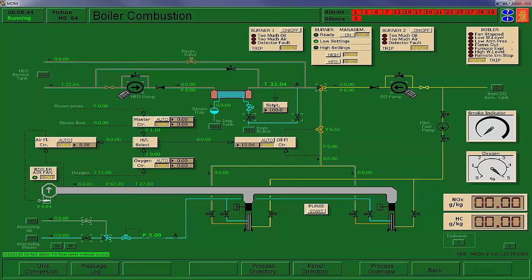Now, any boiler that you go to, you're going to have to play with the settings. But about 15% firing rate for startup is a pretty good average. What we're trying to do is raise the firing rate up a little bit so that initially we can guarantee, or not guarantee, but we hope that the flame will establish. If we try to start out very, very minimalistic, there's a good chance it wouldn't light.